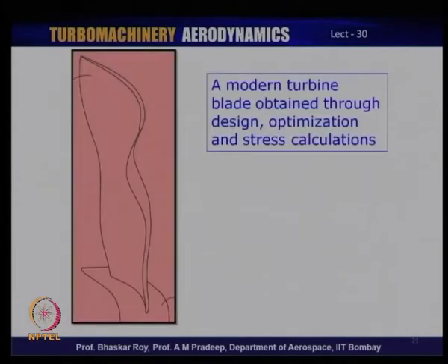I will try to show you a particular refined blade that has been used in turbine design after optimization through the stress calculation and the gas load calculation. And as you can see, the load here is indeed actually factored into the design, and it tells us that the final blade shape may not be a very straight blade. It may have curvilinear shapes similar to what is being shown here, and these are the shapes that you finally get of a rotor, or maybe sometime that of a stator.